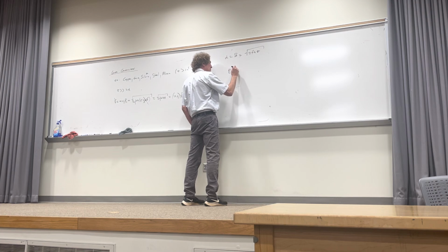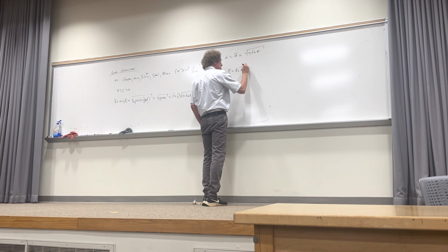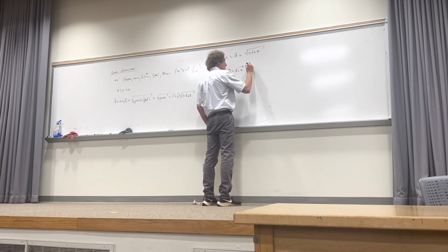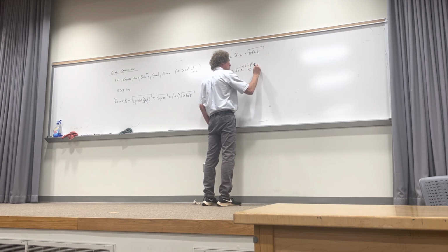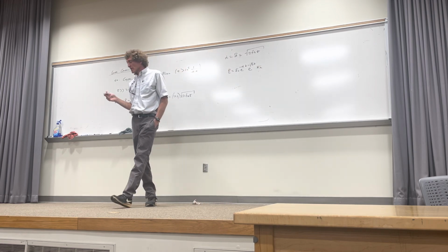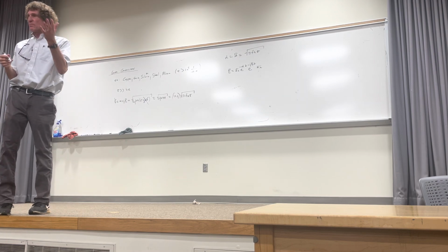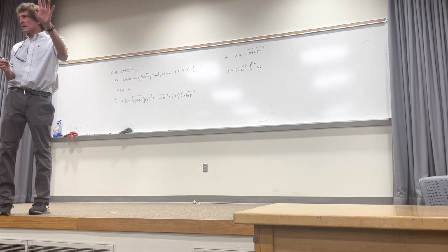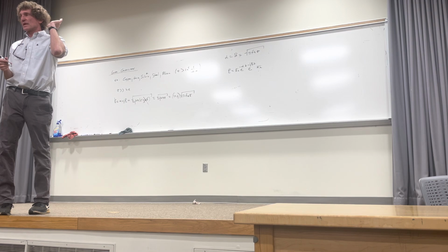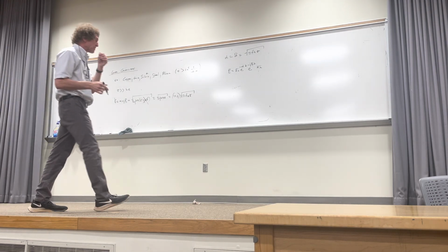The E field itself would have some E0, e to the minus alpha z, e to the minus j beta z, in the a_x direction. Now this is just a propagating wave going in the positive z direction. I want to try to keep this simple. Y'all remember how Wentworth always uses the z direction for propagation and orients the E field in the x direction, just for simplicity, right? He's talking about plane wave propagation.